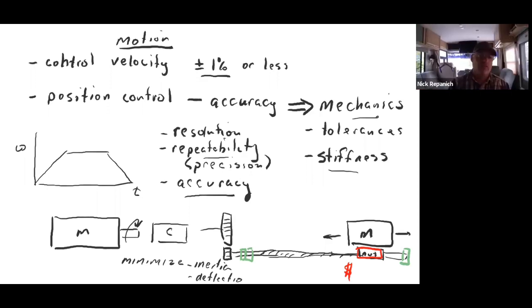Oh, cost. For some reason, motors that you can direct drive loads with are just more expensive than what I would call this. You guys will laugh. This I would call a hot dog style motor, as opposed to one where I was driving the load directly, where I would need a lot more torque, because I'm getting torque multiplication in here and here. Whenever I do gearing or ball screws, you get torque multiplication.